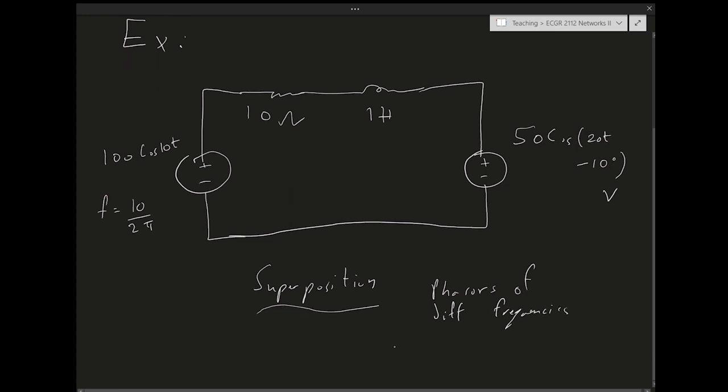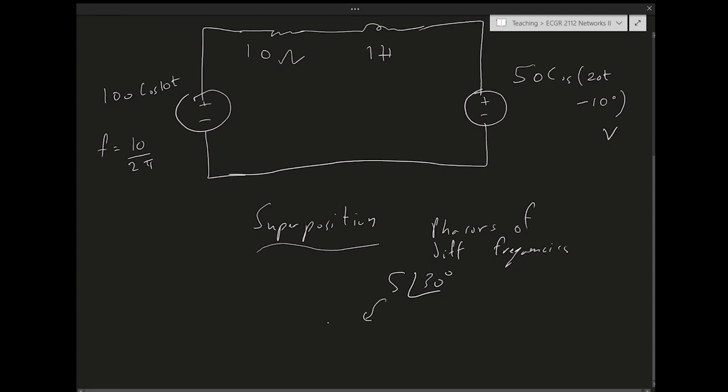Like if I have a phasor 5∠30 degrees that comes from a source that's running at 60 hertz, I cannot directly add it with the phasor, let's say 7∠45 degrees, that's coming from a source that's running at 70 hertz. I cannot add those two phasors directly and expect to get a coherent result. I can only add phasors together that are of the same underlying frequency, right?